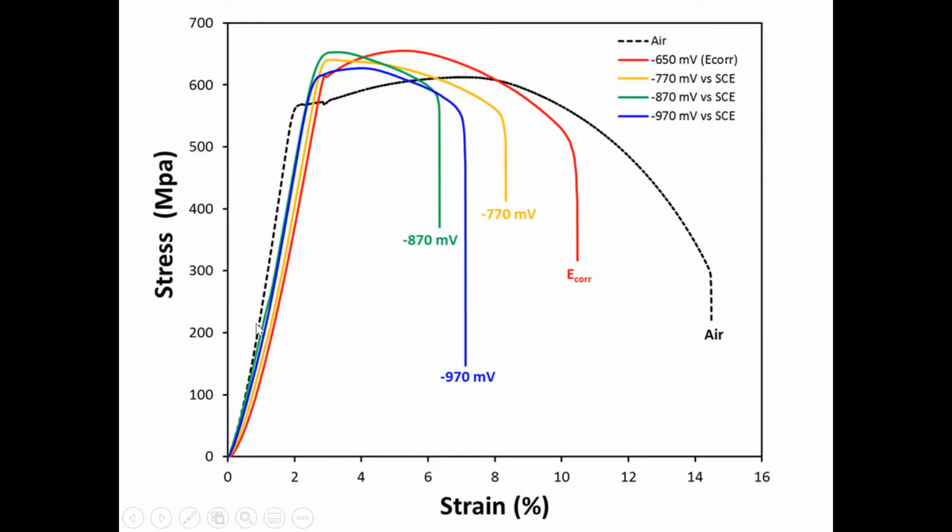So here's the Young's modulus part. Here we're going through the maximum strength. And now it's quite ductile, you can see. So we can start to stretch the material, and the elongation, here's the strain percentage. Let's say that's equivalent to 14% elongation at this point here.